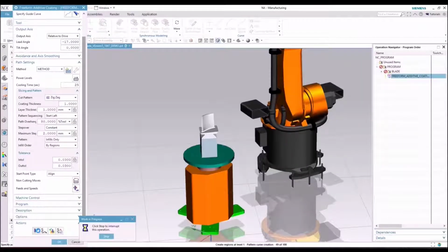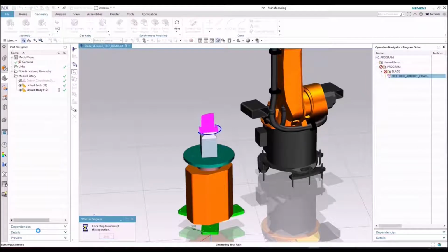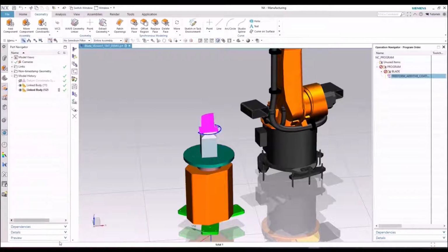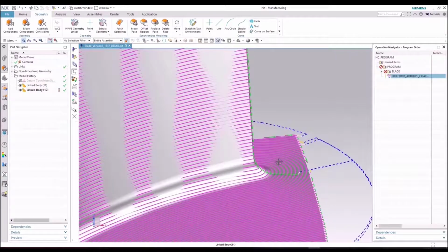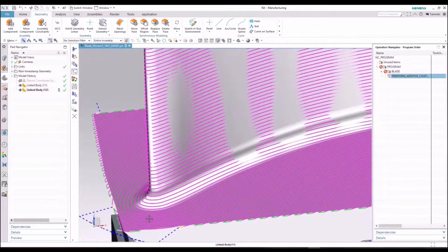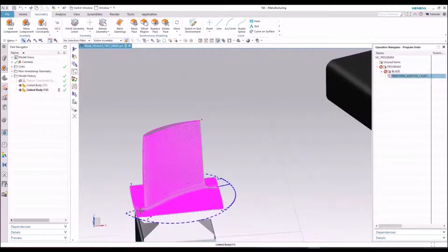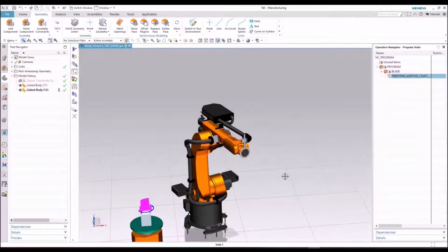Complex surface shapes sometimes require combinations of several tool pathways. NX-CAM allows for generation of separate paths, for example, one along the plate airfoil and another on the adjacent platform surface, which subsequently can be linked by appropriate transfer pathways.